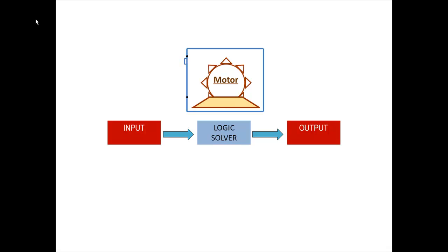In our first circuit example, we will select safety-rated products that make safety calculations very simple, just to start to give an idea of how SISTEMA works. Safety circuits typically consist of an input device, a logic device, and an output device.